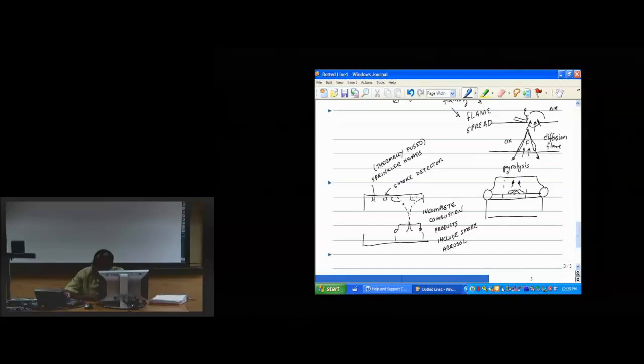So it looks like a gravity wave where, again, in this case, it's a low-density gravity wave that's sweeping across the roof. Across the ceiling. And so the ceiling jet interacts with the smoke detector and also with the sprinkler heads.